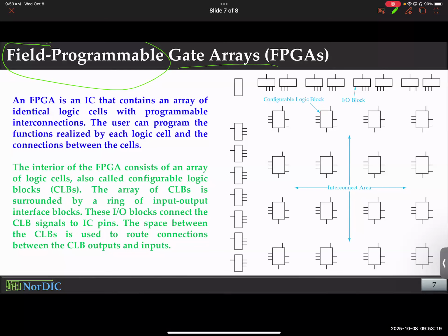That's why you can take an FPGA, incorporate an adder in it, incorporate an arithmetic logic unit in it, you can incorporate a multiplexer, you could change it, reprogram it, erase it, you could do a lot of stuff, because this is, again, the term field programmable. If you change the field, the programming changes, that's all. But mask programmable stuff is basically inflexible. You cannot change the programming at all after it is designed. Okay. You might be wondering, why would you even design or use a mask? Obviously, nowadays we try not to do that at all.